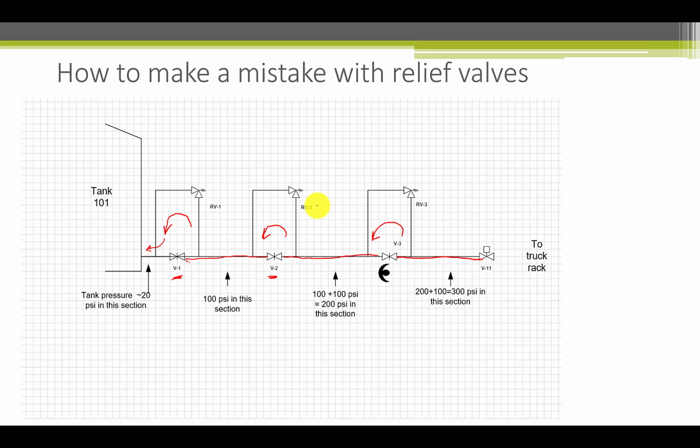Now, why is this the case? Well, to understand that, you have to understand the physics of a piece of pipe that has no air in it but is filled with a hydrocarbon. It turns out that there is about an 80 psi per degree Fahrenheit pressure increase.